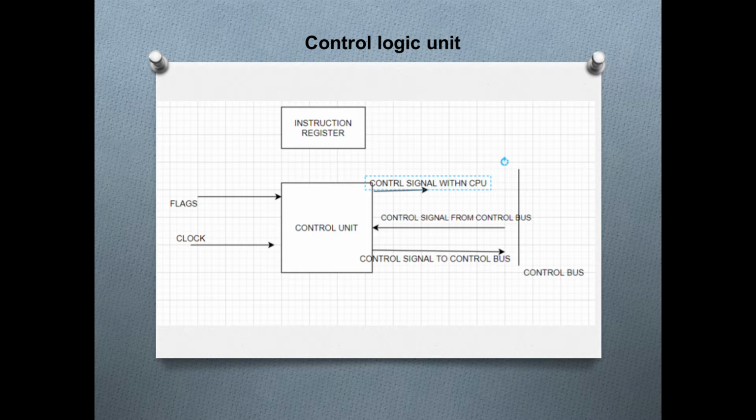The control bus generates control signals such as acknowledgement and interrupt signals, which are sent to the control unit. The clock system is supported by the basic clock module that includes support from a watch crystal oscillator, an internal very low power frequency oscillator, and an internally digitally controlled oscillator.